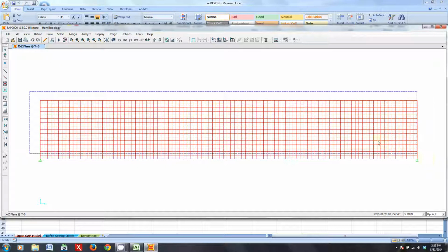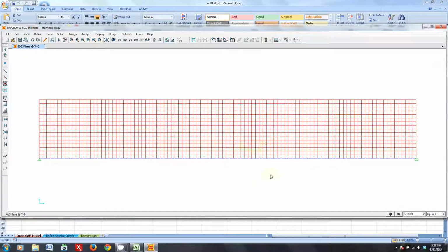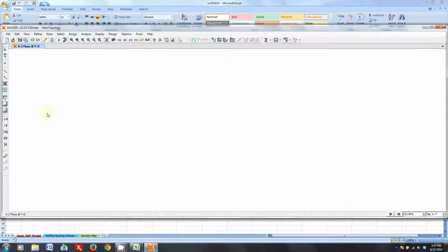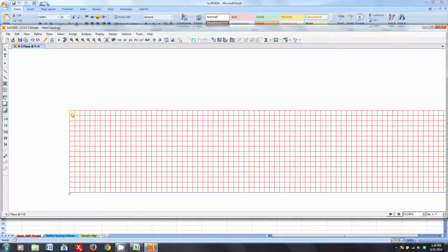If you remember maybe from the learning exercise we did with treating beams like trusses and so forth, I'm using that same principle and just filling it up with area elements or shell elements, and each one of these little pieces here is a shell. So what I'm going to do is run my model, get all the data results from that, and then increment based on how much stress is in each individual shell element in this grid. I'm going to change the density of this particular cell, for each cell.